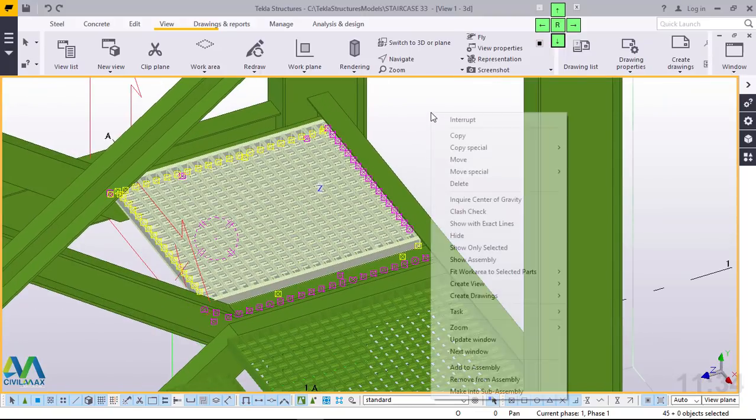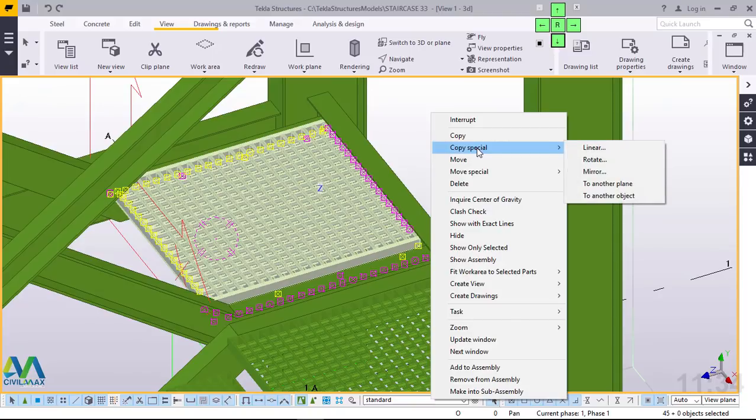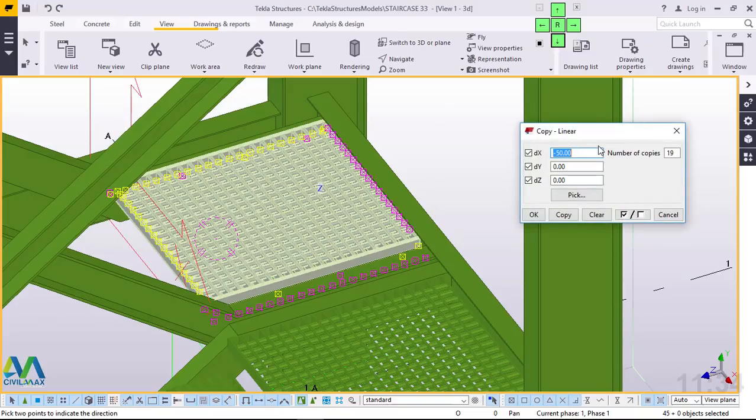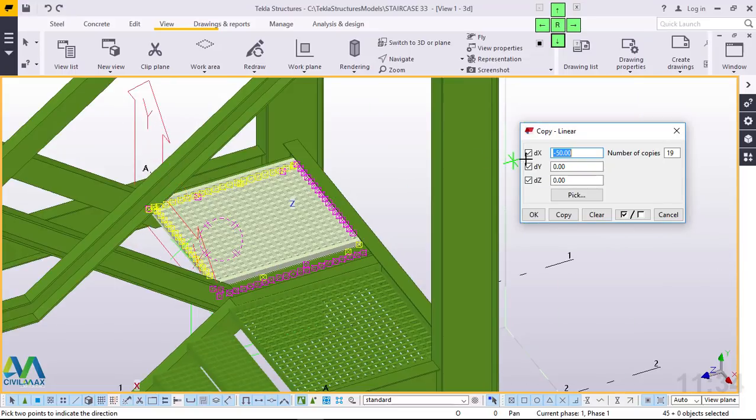But now we'll right click and come to Spatial Copy, then come to Linear, then under linear, now we'll follow this axis. We'll not work with the Z axis, we'll follow this axis. Now we'll change that to 0, then we'll feed -50 millimeter down,